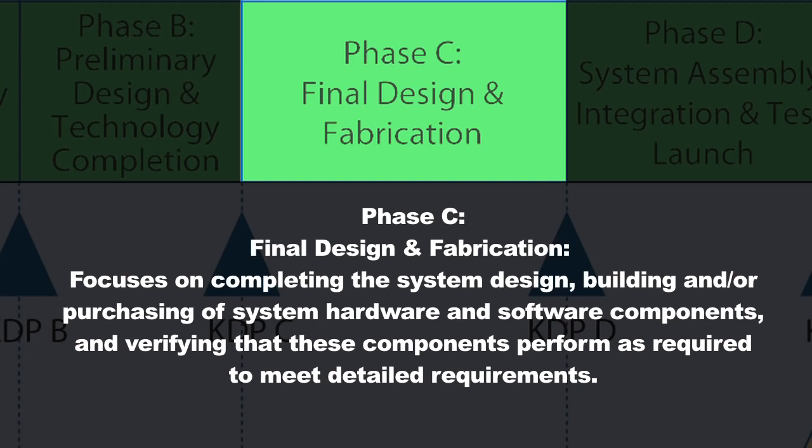So once this rocket is chosen, now the team has to go back and complete the design of the satellite to make sure it will properly interface with the rocket that's been chosen, the launch vehicle, and that it also is going to be able to survive the launch environment. Every rocket has a different launch environment, the vibration environment, the acoustic environment, and again, the technical interface between the spacecraft and the launch vehicle. So the satellite team needs to go back and refine their design to make sure it's going to be compatible with the specific vehicle that they're going to be launching on.